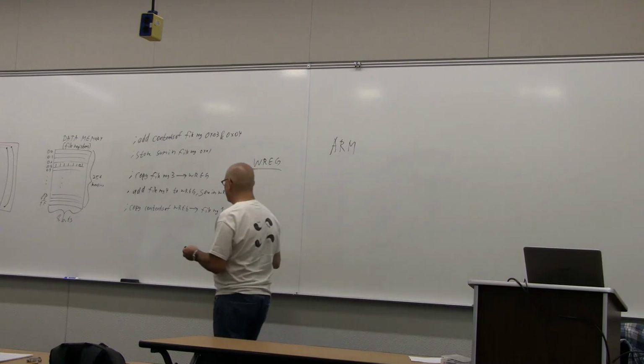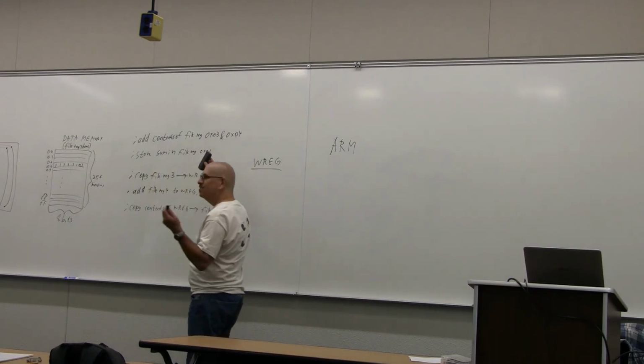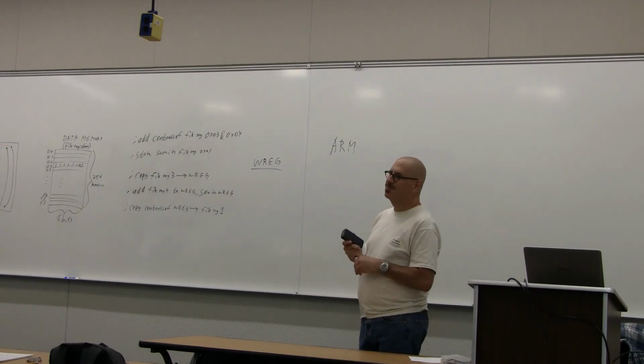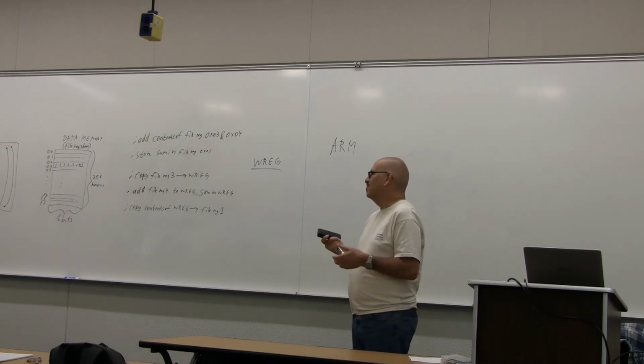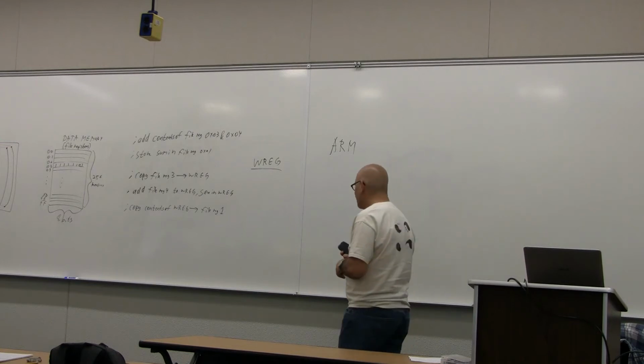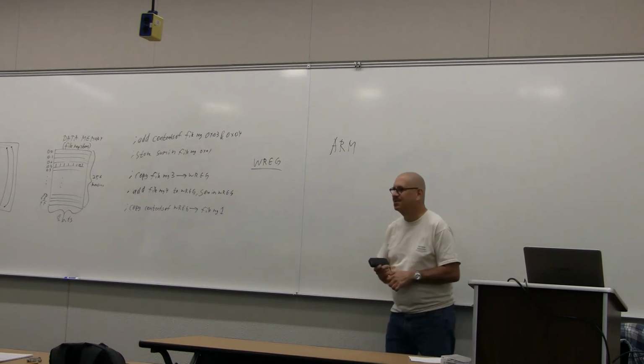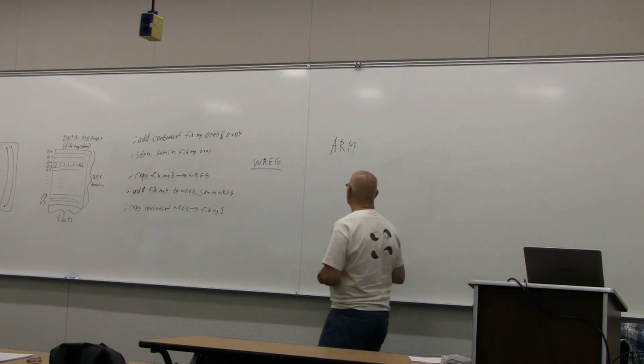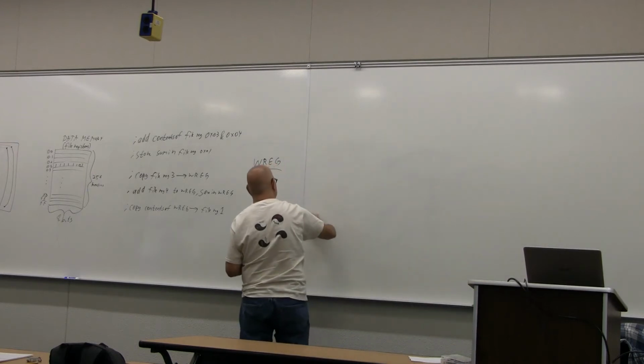So for what we're doing in here, we don't really care about speed. We're running with a clock of around 31 kilohertz, which is pretty slow anyway. But if it takes 10 microseconds for your LED to turn on, it's not going to bother us. So this will work perfectly fine for us.